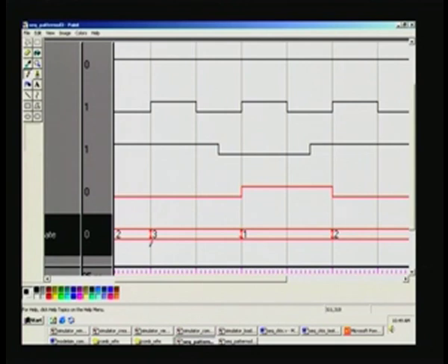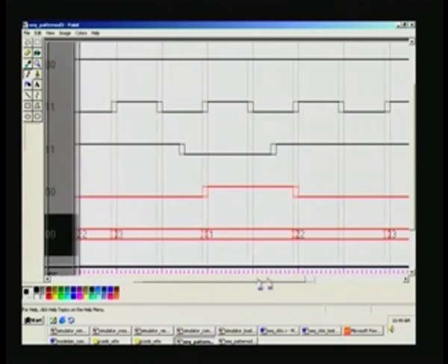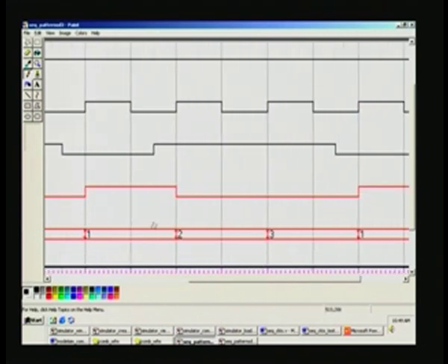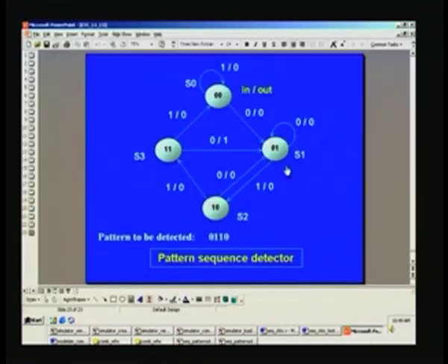So, next, we have already gone from third state to 1 state, and now let us see 1. So, for 1 what is it that we are looking into? It is 1 here, this is input here. For the earlier thing we had sensed this as 0, now at the next positive edge only you have to see. So, now you will be sensing 1 for the input in state 1. So, let us have a look. In state 1 if it is 1, it should take you to S2 here. We had gone to and fro earlier, we are coming back, right.